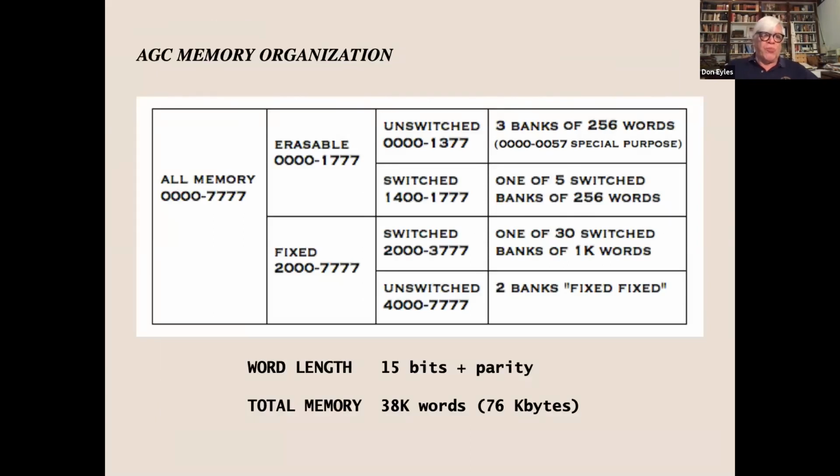was the way the erasable and fixed memory were arranged, where there were certain parts of each of those memories which were always in place, shall we say, but another part which could be switched to any of several banks of memory. Now, that may sound burdensome, if you needed to deal with something that was in a different bank, and there were subroutines to help you do that.